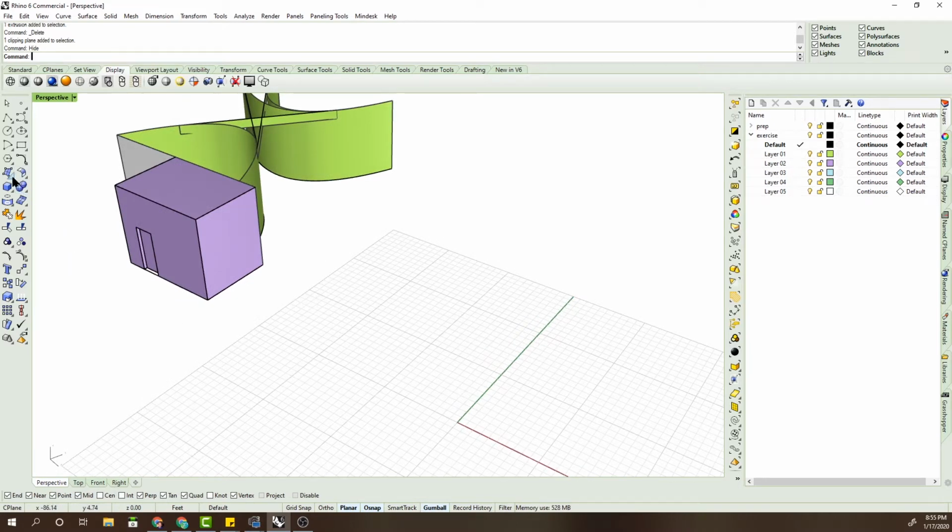So I really like to use the 3-point rectangular command. If you just use the regular rectangle, you can hit 3-point right up here, and always keep in mind these sub options after you do a basic rectangle. So I'm gonna hit 3-point, and then if I have my snaps on here rather than disabled, if I have them on by default, and I've got center line and midpoint, different things, I can hover and it's gonna hit the endpoint there. Now when I click, as I go here, it's going to start snapping around.